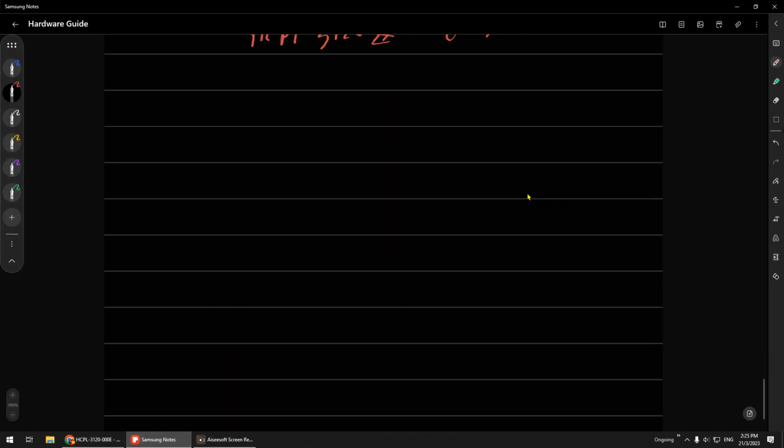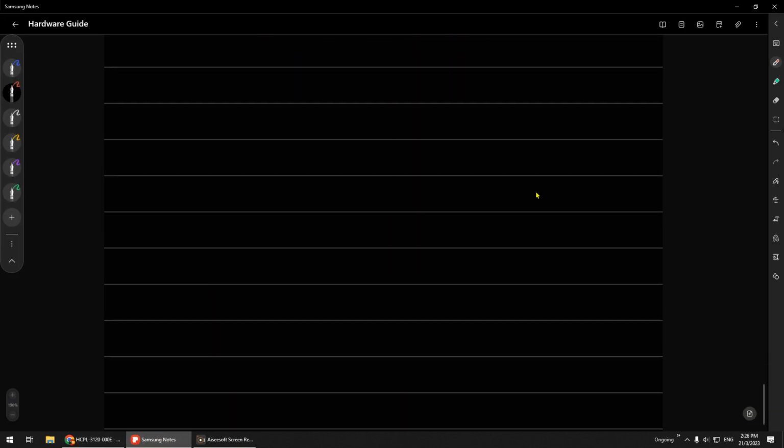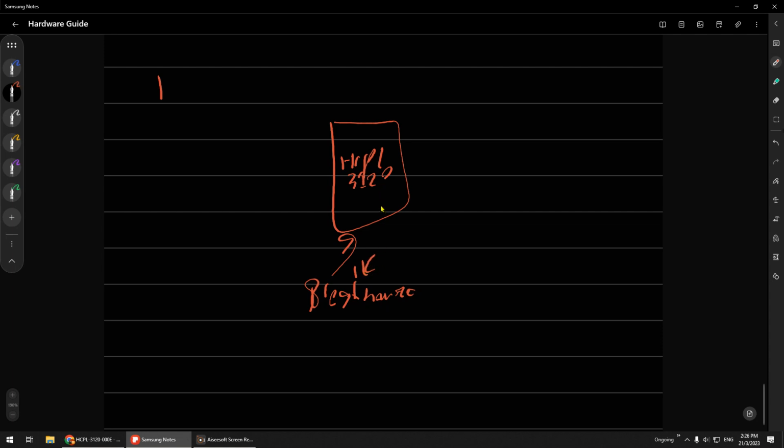Okay, so let me move here. And of course you have to put it in the Excel like I showed before. First thing you have to buy the optocoupler, SCPL 3120, and of course you have to buy the 8 leg IC housing. For this you cannot just solder it into the PCB. You need to have a housing, if not it will be damaged.